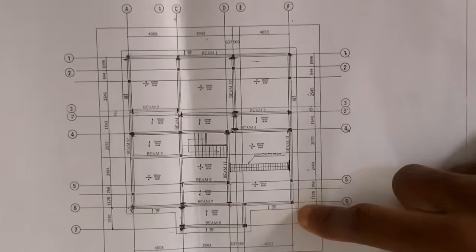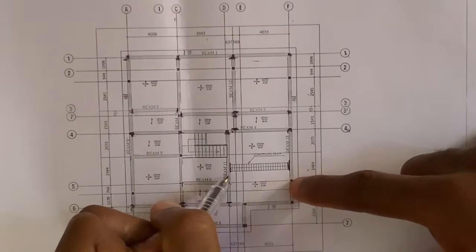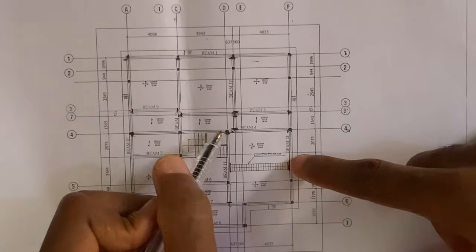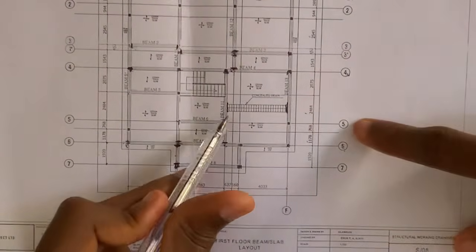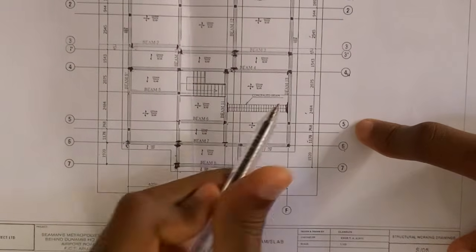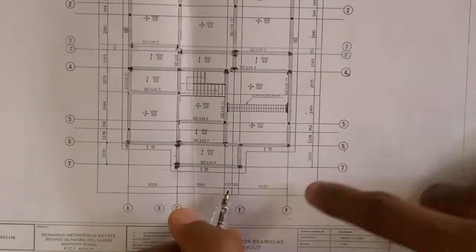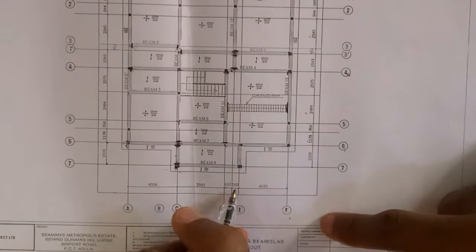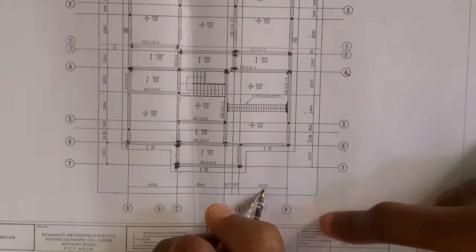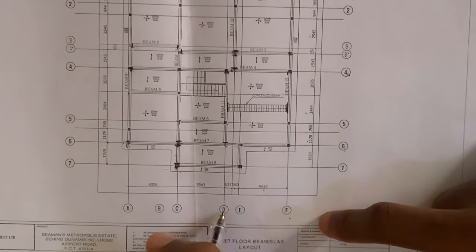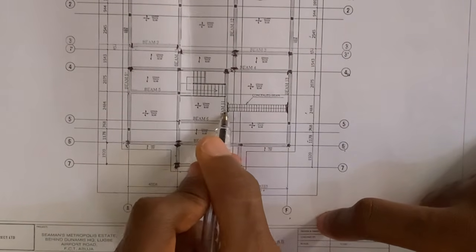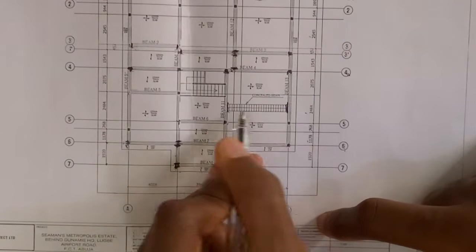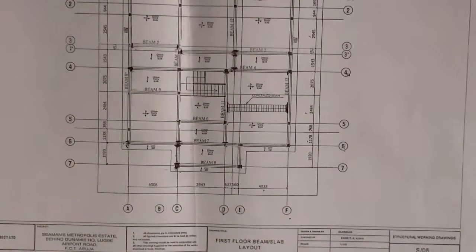So how do we do that now? If you look at the dimensions that we have here, if you trace this concealed beam down here, you can see we've traced it to call out D. From this center point we trace it to call out D, and from this point to call out F. So we can add these three dimensions, 637, 560, and 4033, together to get the total dimension from call out D to call out F. Then we minus half of the thickness of this beam on both sides to give us the in dimension for this concealed beam. So now let's measure.